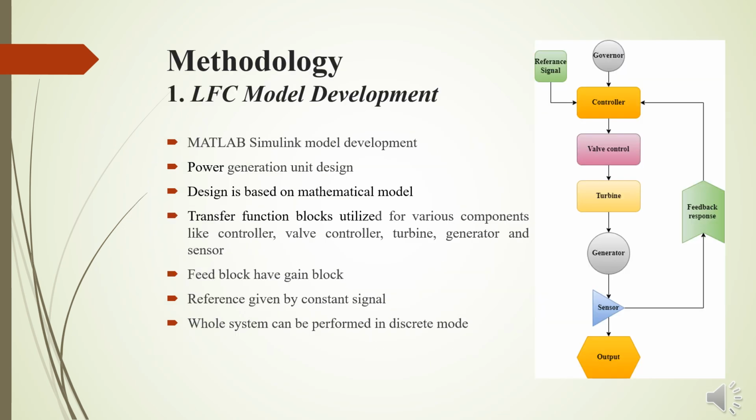In methodology, first I discuss LFC model development. LFC means load frequency control. Here we can see the flowchart of this model. This development is based on MATLAB Simulink and I generated the MATLAB model according to the mathematical development by using transfer function blocks. These blocks are utilized for various components like controller, valve controller, turbine, generator, sensors. A similar feedback block is used for feedback response, and our reference signal should be constant, so a constant block is utilized for the reference signal.